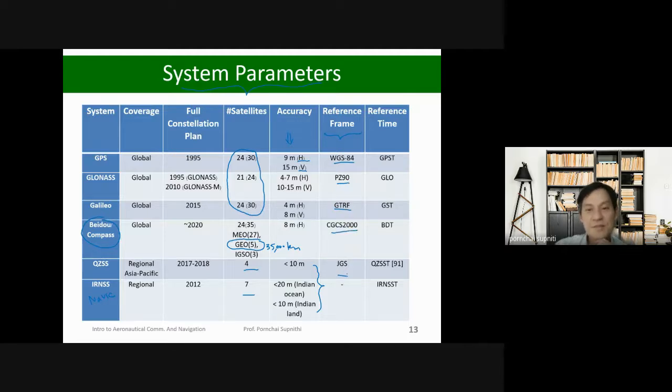And if you get XYZ from the GNSS system, that is the positioning from a certain coordinate system, but it's not the exact XYZ on your surface. So this correction has to be made, and the correction depending on the surface is based on this reference frame.